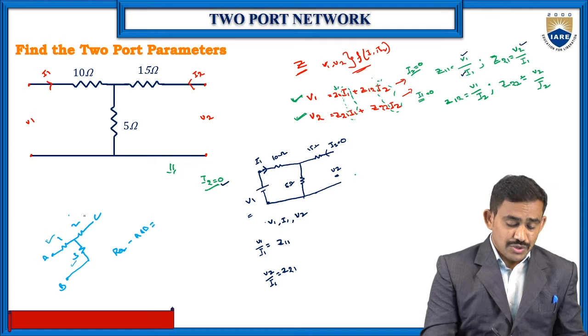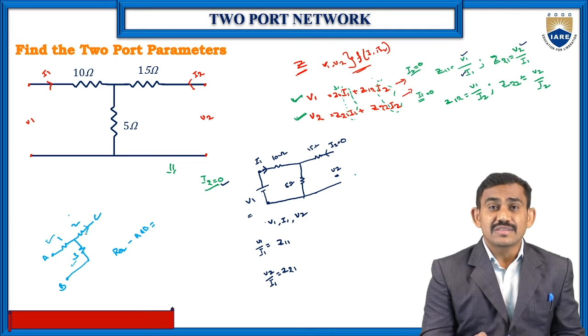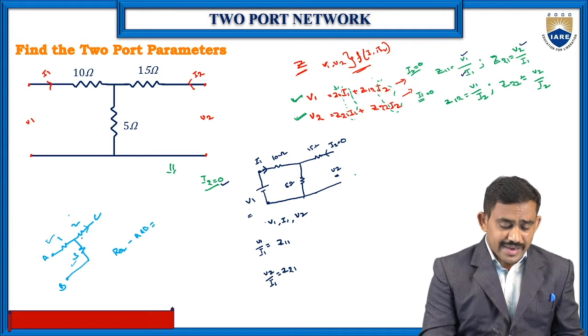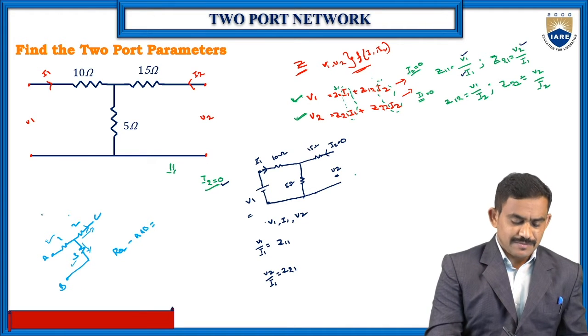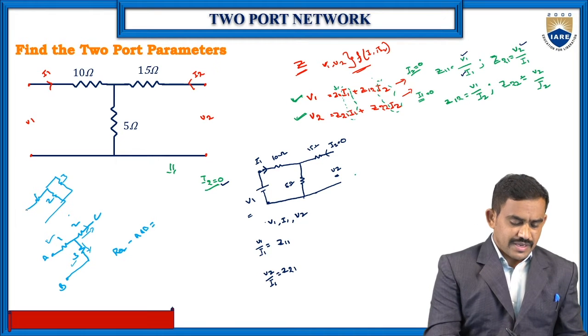What about the 2 ohms? The 2 ohms is an open condition, so there is no current flow. Current flows through only the 3 ohms. And one more similar condition: again I have 3 resistors, 1, 2 and 3, between A and B.